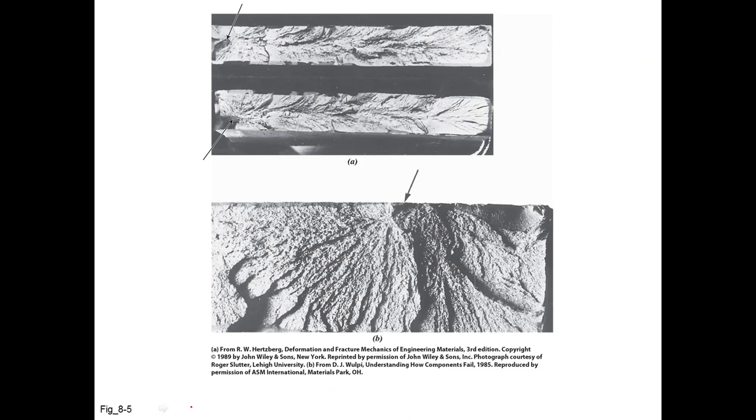So here, fractures occur with little plastic deformation, and it's most prevalent in metals with few slip systems, particularly hexagonal close-packed systems, zinc, magnesium, and recall the zinc single crystal case that we looked at earlier, as well as ceramics that have few slip systems and atom jump distances that are quite far compared to the metal case.